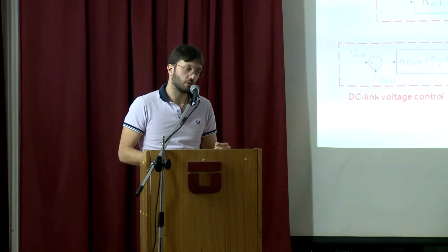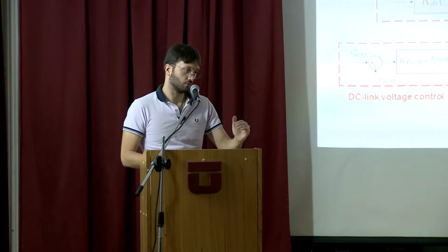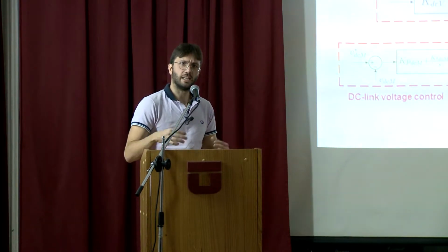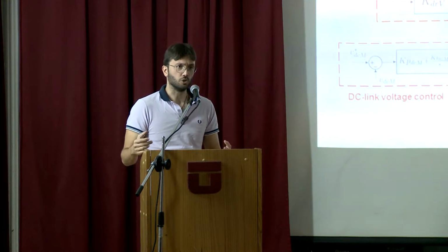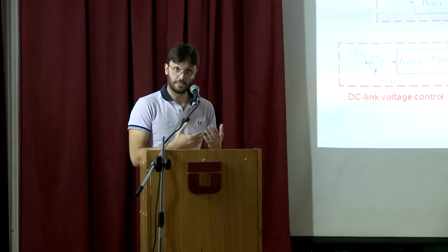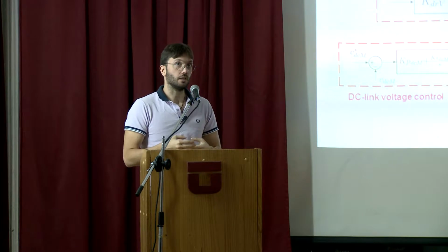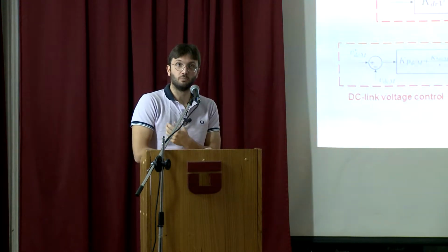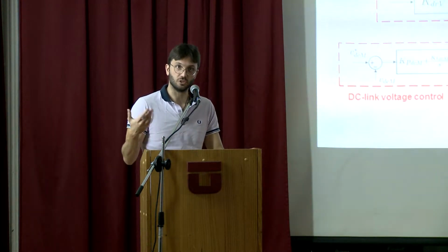If the voltage goes down, we increase the reactive power injection or absorption to lift the voltage up. It is basically what a STATCOM does. So sometimes you are forced to have a big power electronics equipment like a STATCOM, a static compensator, that is basically doing what for a current controlled power converter comes natural: controlling some current, controlling some reactive power.